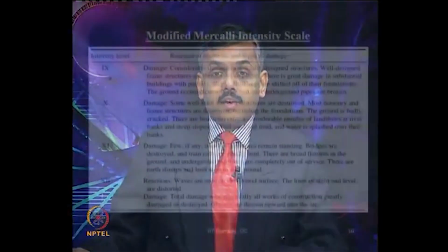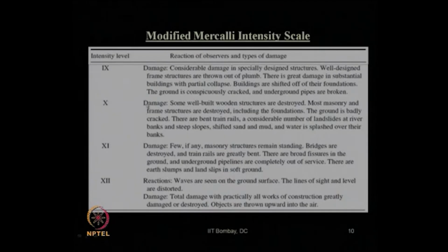So, the next intensity level is intensity level 9 in this MMI scale. The damage is considerable damage. Of course, reaction does not matter now, since everybody is feeling it from the previous two intensity levels onwards. So, we are now talking about the damage level, which will help us identify different intensity levels. The damage is considerable in specially designed structures, that is, even engineered design structures